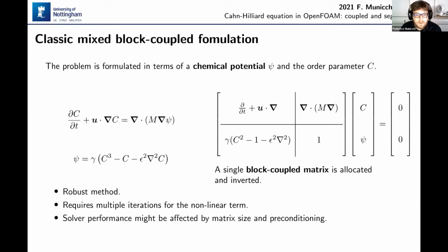Jumping into the numerics, a first approach that is often used, especially in finite element, is the so-called mixed formulation, normally solved using block-coupled matrices. This can be done in OpenFOAM, especially in foam-extend. It's quite straightforward. You define a chemical potential, in this case psi.